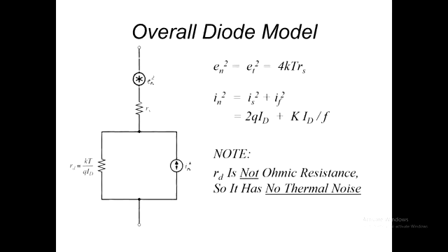And some people call it 26 millivolts because they're thinking of hotter temperatures, 25 degrees Celsius. But basically, if you use 25 millivolts, that's a happy figure because it's easy to manipulate arithmetically.